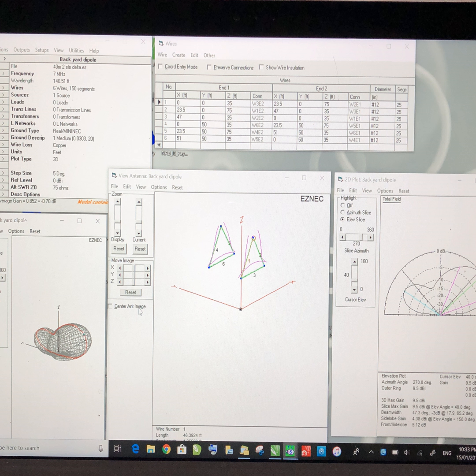And it's the same if you're designing multi-element wire beams. Even if it's just a 2-element beam, you can get a fairly good idea of the effect of the spacing, the height above ground, the front to back ratio, and the enhancement that having a second element on a beam will give you. And one of the big advantages of having the second element is it lowers the angle of radiation in the desired direction.